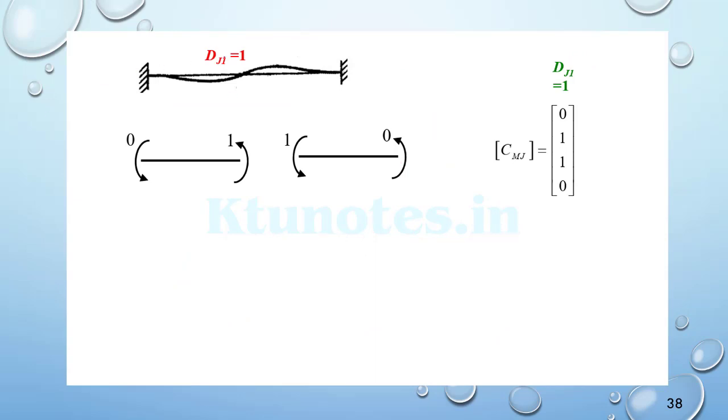So in the stiffness method, you will be applying a unit deformation, and you are supposed to find the reaction which is required to make the unit rotation. Here is such a rotation because there is a change in angle, there is no displacement in the vertical as well as the horizontal directions.